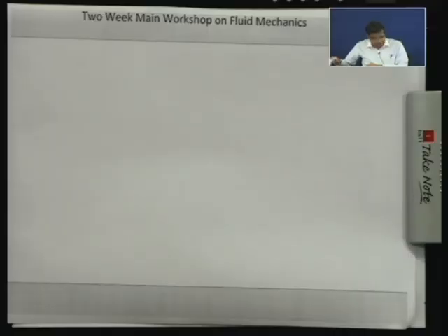So, therefore, this concept gave birth to the axial flow turbine, where the flow is in the axial direction and the blades are made in such a way that they give a much higher cross sectional area as compared to a radial flow, so that we can accommodate more flow rate, which can work efficiently at a relatively lower head. And this is the concept. For lack of time I cannot explain this in more detail. The Kaplan turbine, this is where